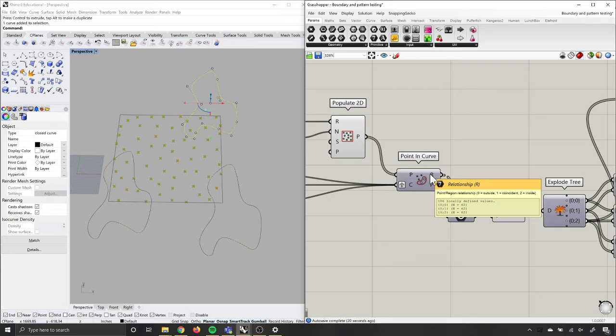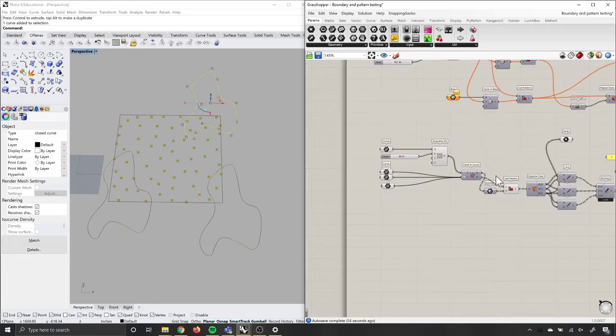This is a bit different than how the BREP one will work, where it's really just using zeros and ones as true and false. In our case, we're just looking for if they're directly inside. So they work like Booleans, because if you have something that's a 1 or a 2, it will just read as true, while the 0 will always read as false. But the reason the list is 62 long is because it's testing everything here.